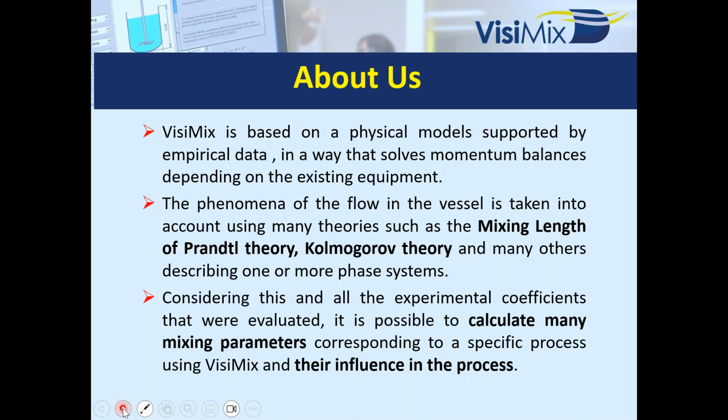Once we connect the results from the momentum balance, that is the velocity, and we integrate the data that we have from different adaptations of models to the stirring vessel operation and geometry, we will be able not only to generate power per volume, shear rate, and mixing times, we're able to connect it to the main and intuitive parameters that every process engineer would like to know and to keep fixed.